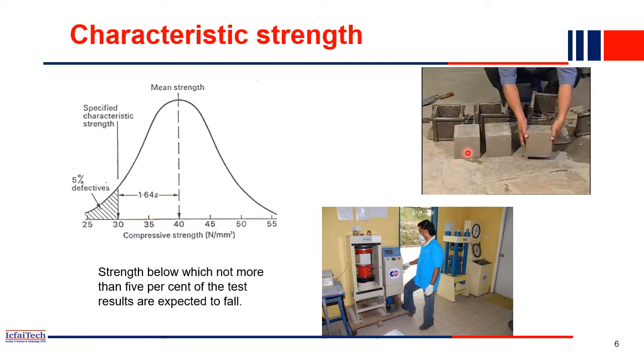Now these four things can be added in different manner also. Sometimes you can add more cement to the concrete. Sometimes you may add more coarse aggregate into the concrete. Depending upon these three or four ingredients, if you mix them in different proportions, you will get different grades of concrete. Some concrete will be very strong, where you use more cement content. If you give less cement content, then the strength of the concrete will be less. So depending on the proportion of these ingredients, different strengths of concrete will be achieved.